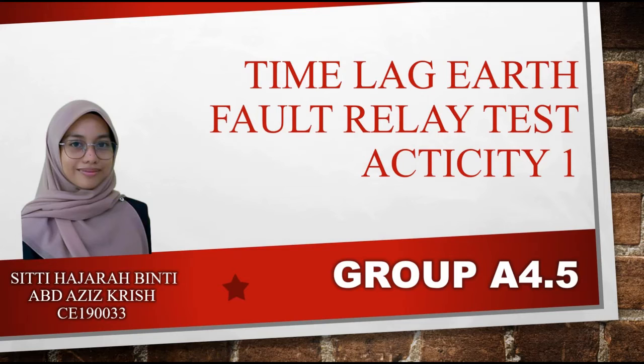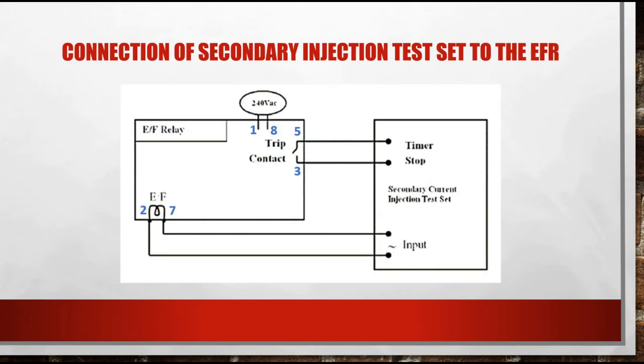So I will continue to explain the connection of the secondary injection test set to the EFR. Based on this diagram, we can see the pins in the EFR that will be connected to the secondary current injection test set, which is a Mega SCITS 100. These are the pins included in the EFR.